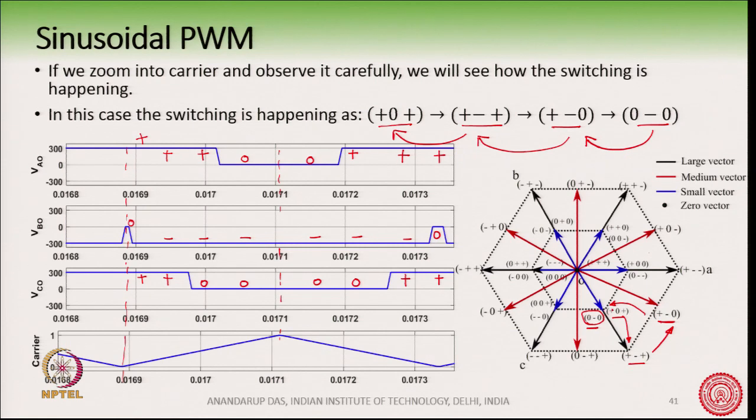First we go clockwise and then we go anti-clockwise like that. Okay. So, one way like this and the other way like this. So, this is very consistent with the space vector PWM strategy that we had also developed earlier for a 2-level converter, but now we are centering our center or pivot vector here. This is the start and end vector. So, as we said, these are the 6 centers, the 6 pivot vectors from which the switching starts, and this is an example of such a switching.